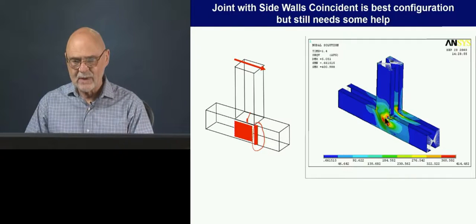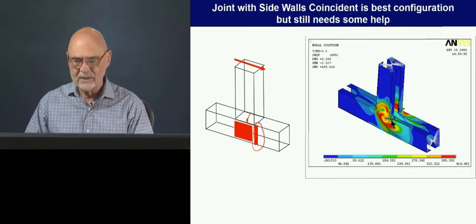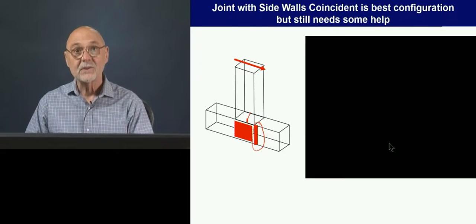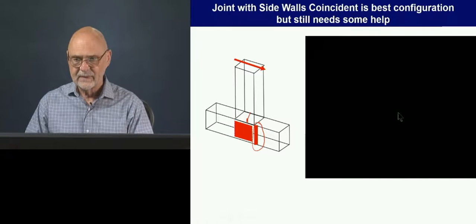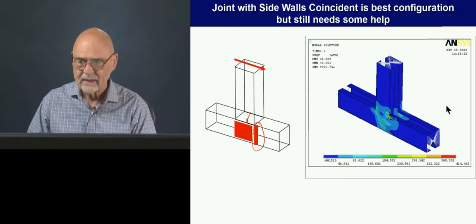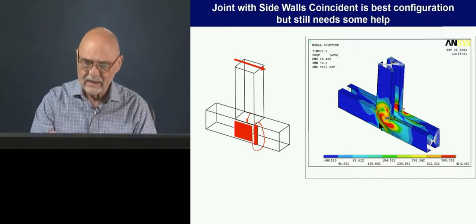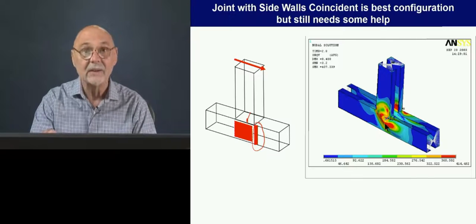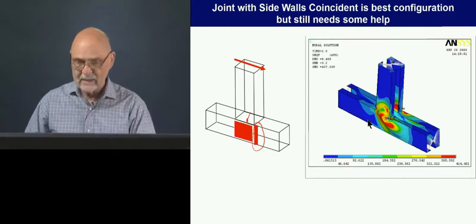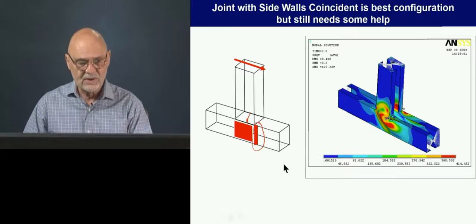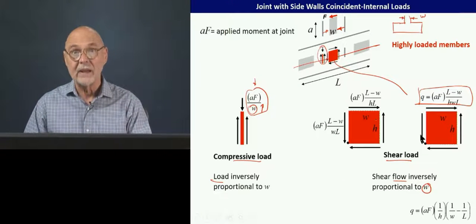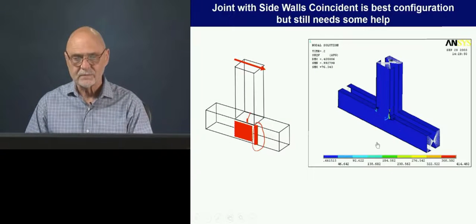So you see that this shear panel here is kind of buckling, and we're compressing this right in here. So that area has buckled. Let me play it again. This area here will start to see the buckle, and then we have diagonal buckles here. Okay, and this kind of loading is very consistent with our little analysis that we did here.